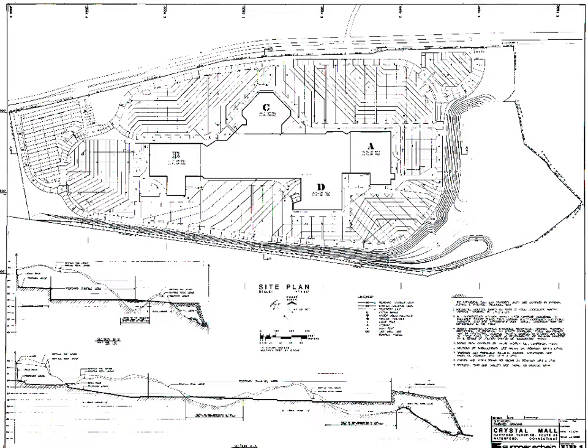And usually, when people draw engineering sections like this, they exaggerate the vertical scale. So it's not exactly that amazingly steep, but you exaggerate it so you can clearly see the differences in elevation across the site. And you'll notice the lighter existing slope shown in those sections and the much heavier, darker proposed slope.